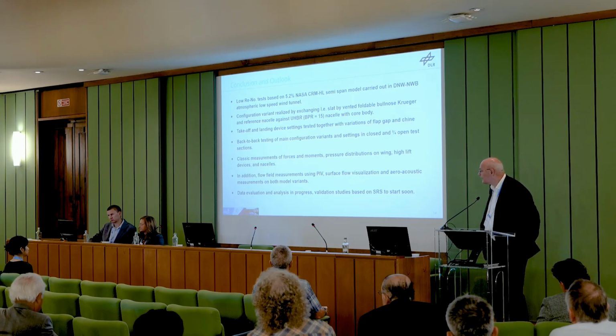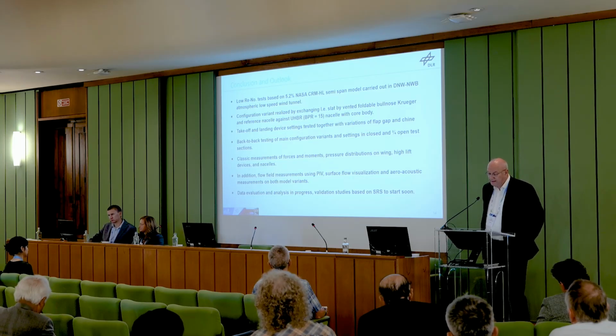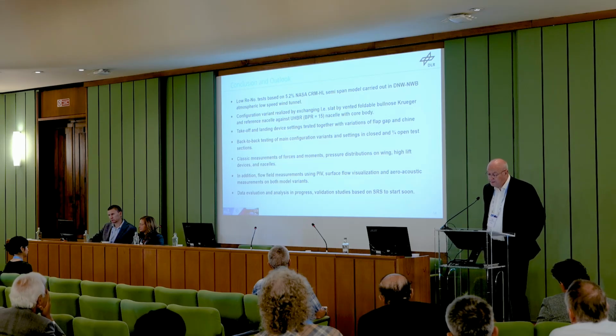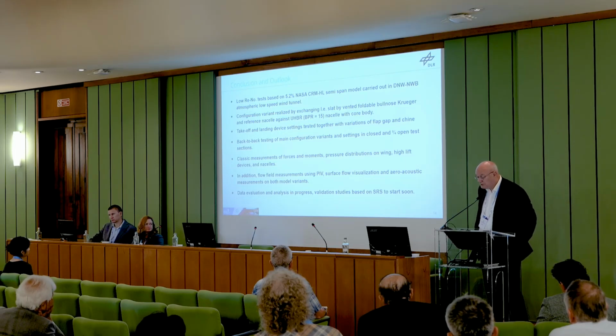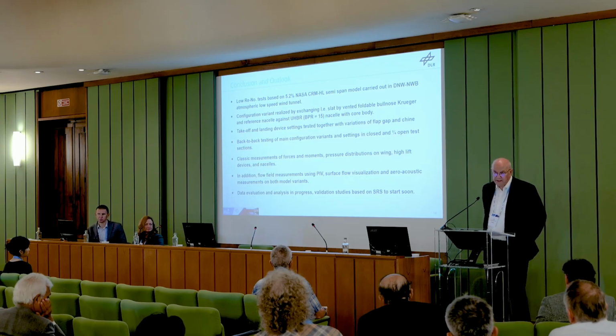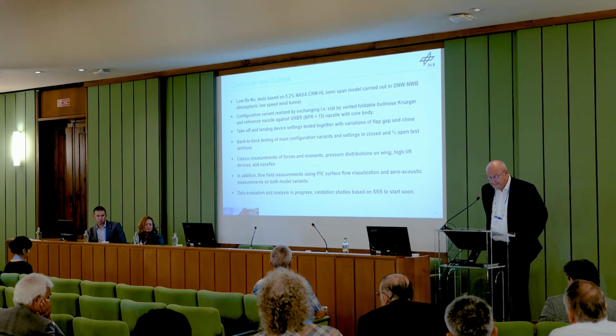This has been mentioned by Clark. So we checked a sealed or partly sealed and an open gap, and also did variations of the chine as a side study. We did back-to-back testing of the main configuration variants and settings in the closed and the three-quarter open test sections, and performed classic measurements of forces, moments, and pressures on the wing, but also did some flow field measurements using PIV, flow surface visualization, and aeroacoustic measurements on both variants.